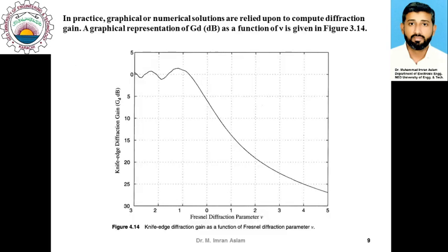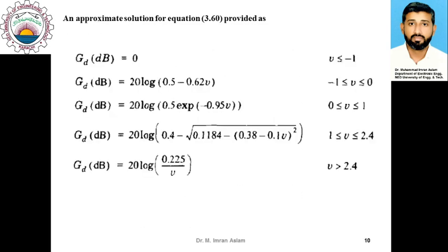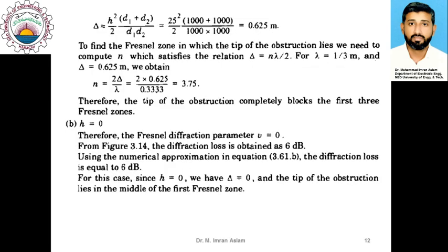We can calculate this diffraction loss from this curve as well as from these approximate relationships. So this concludes our discussion on diffraction loss and Fresnel diffraction, and we use the knife edge diffraction parameter to numerically calculate the diffraction loss. So we stop our discussion here.